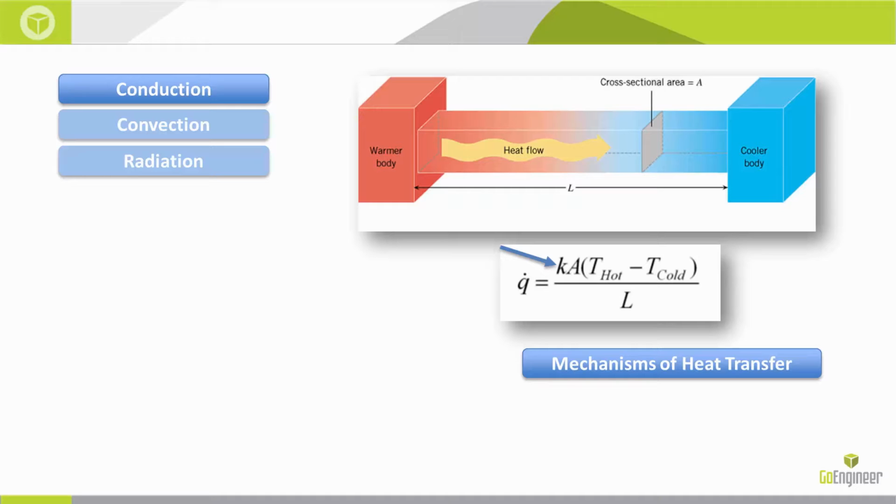So essentially, if you're running a simple conduction problem inside SolidWorks, three key variables are involved. You're either specifying the temperatures at the hot and the cold end to see the rate of heat transfer across the product, or you're specifying how much heat is entering the system and what the temperature distribution of your entire system is by virtue of the heat. So you essentially need to define two of these three things.